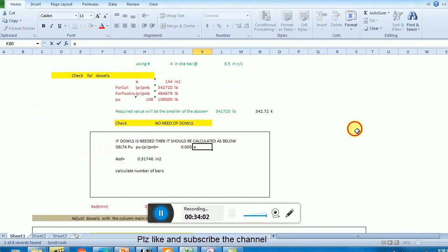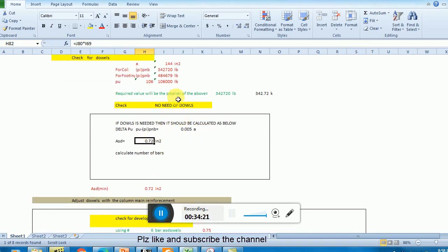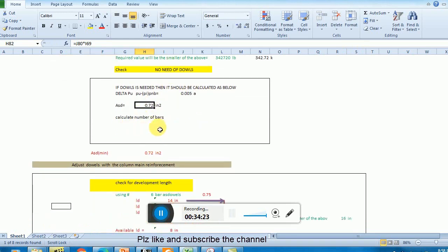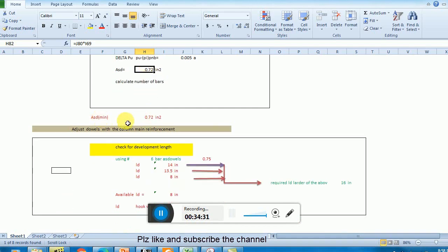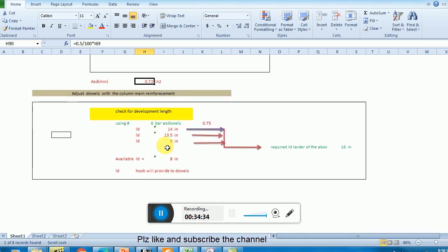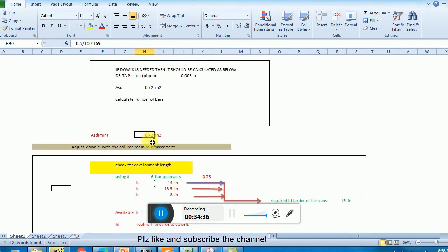If you don't understand, please watch this. And similarly 0.005, this is the ACI minimum criterion for dowels. You have to use 0.5% of the area of the column, and therefore I am inserting the actual formula, that is this factor 0.5 divided by 100 gives me 0.005. So I multiply 0.005 with A, I got 0.72, and remember, this is very important. As we are providing 4 bars, this is my Asd.